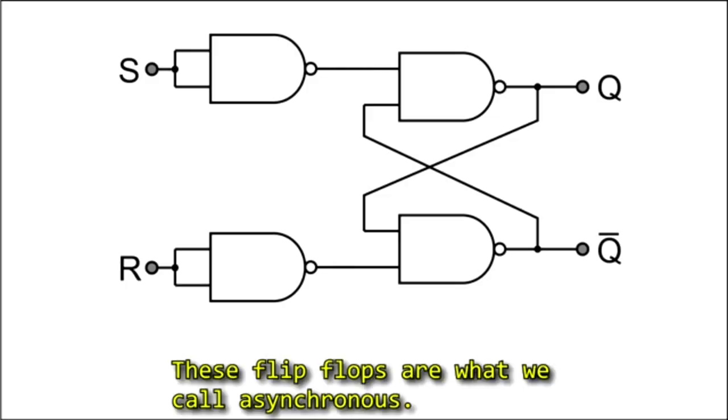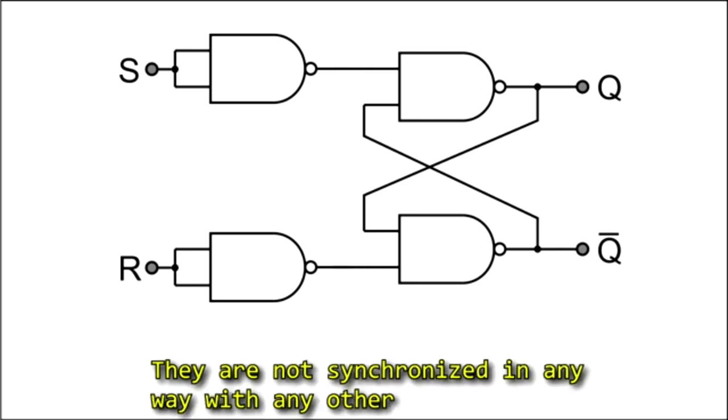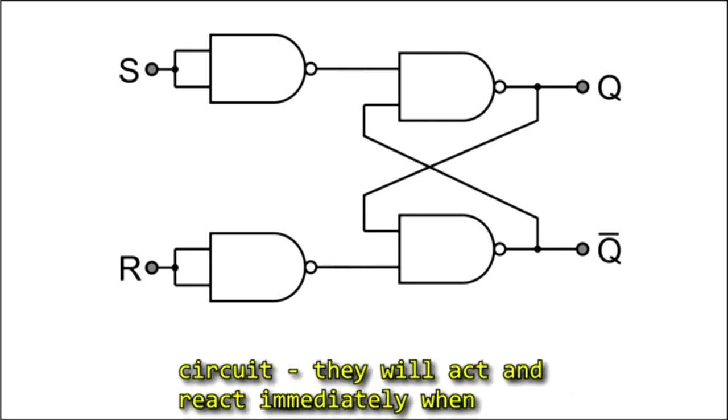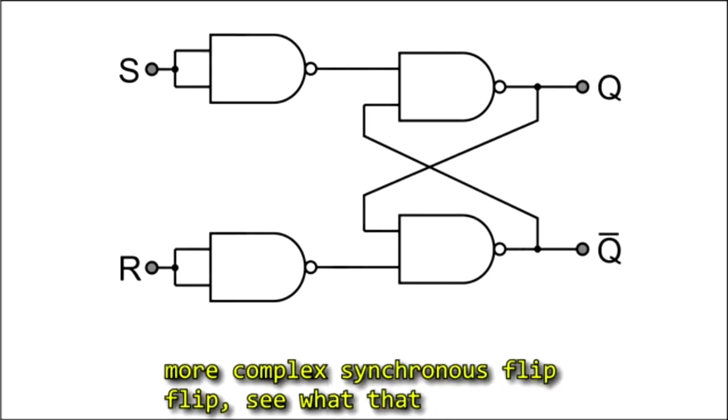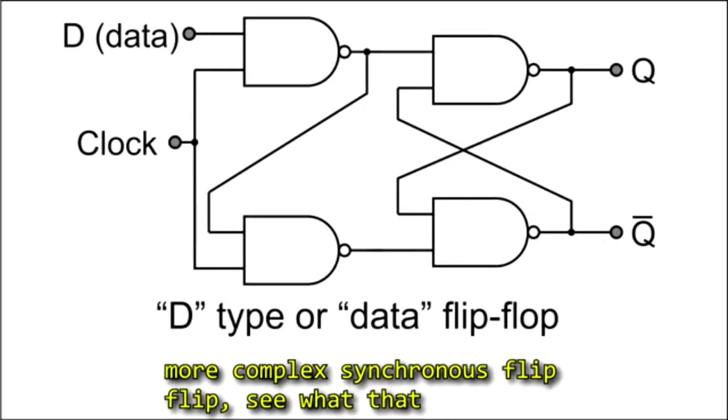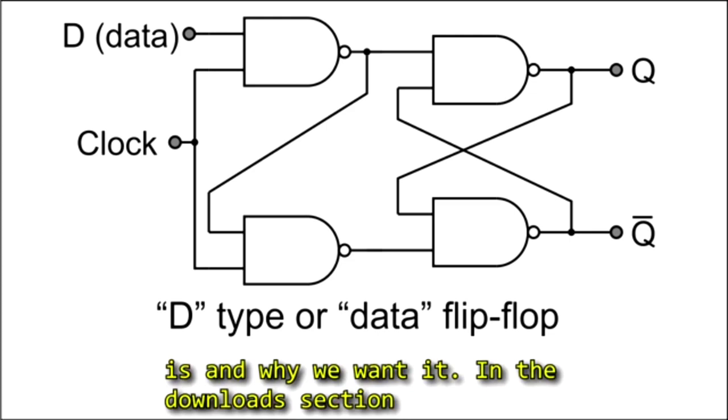These flip-flops are what we call asynchronous. They are not synchronized in any way with any other circuit. They will act and react immediately when we either send a set or reset signal. Let's build a more complex synchronous flip-flop, see what that is and why we want it.